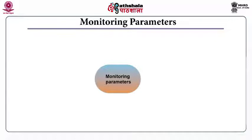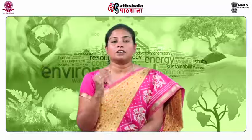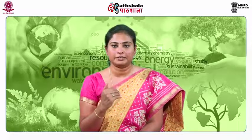Now, let us discuss the various monitoring parameters to facilitate faster waste degradation in the landfill bioreactor. The different monitoring parameters are moisture, temperature, gas flow and quality, waste density and settlement, leachate yield and quantity, quality and leachate flux. Continuous monitoring should be done for landfill bioreactors so that operational failures can be minimized.